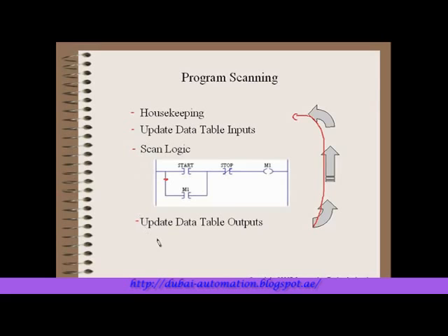This is called the PLC program scan, and a PLC program will scan repetitively as it's running, constantly updating its outputs and constantly checking its inputs, and that's the important thing to remember about programming in a PLC. PLC program scans are very quick. You will see them on the order of milliseconds and microseconds. So we're looking at information that's being processed very quickly, and it obviously has to be able to monitor relays, encoders and other fast-acting devices out in the field.